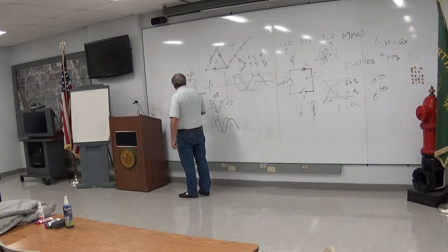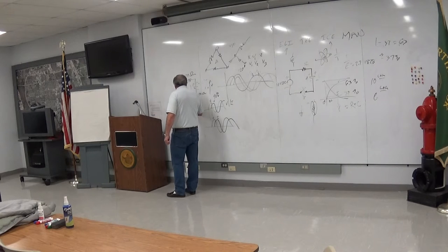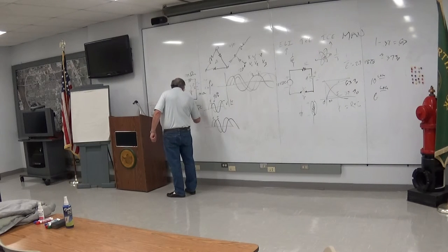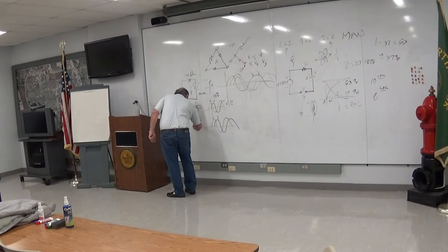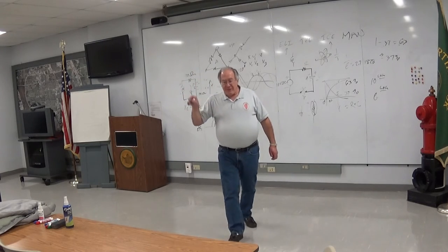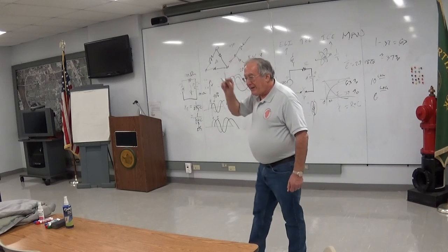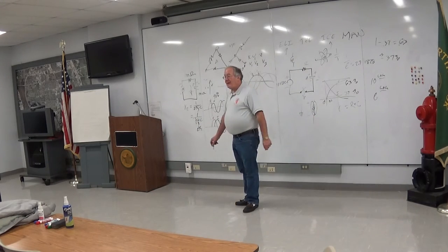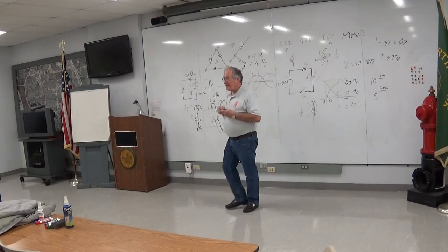We know that this is a function of frequency, so X sub C has to be 1 over 2 pi times the frequency times the capacitance, or in short form 1 over j omega C. Omega is 2 pi f, the frequency, the number of times you turn the circle, 2 pi radians per rotation. And the j is just a bookkeeping device.